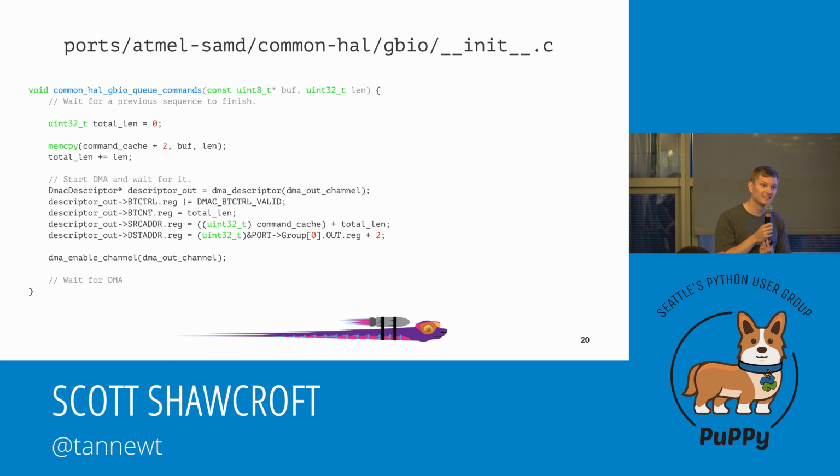direct memory access. It's something that helps the CPU. Imagine that you have a WAV file that's thousands and thousands of bytes long. If the CPU is responsible for copying that from here to here, you'd use a lot of CPU cycles. What DMA allows you to do, and what we're doing here, is saying: we have this thing, and we want it to copy over here at some pace. But once I tell you that I want that to happen, just do it. Don't worry about the CPU doing it. The CPU doesn't need to worry about it.